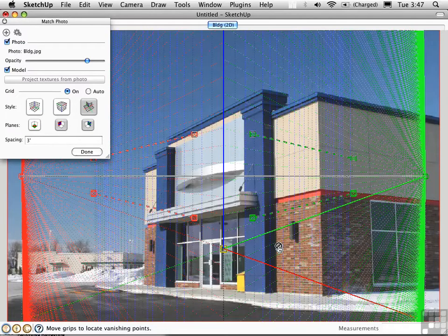In the first part, we'll align the perspective implied in the photograph up to the coordinates of our three-dimensional space. That way, the red, green, blue axes will match up with those implied in the photo. Then we'll create a very simple model composed primarily of boxes that are extruded in different planes. Then we'll go ahead and map some of the pixels from the original photo onto the model to create a texture-mapped model.